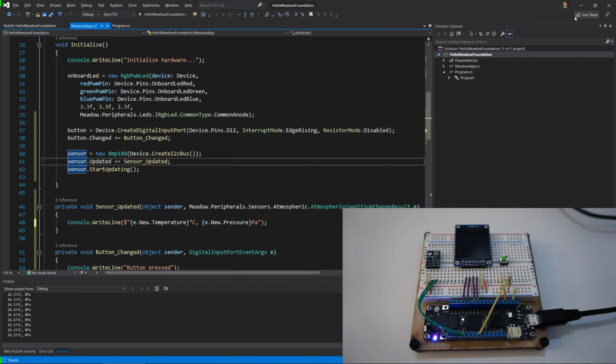And so what that really lets us do is lets Meadow control the speed. So Meadow controls that clock, and it dictates how fast data goes back and forth. And then there's 2 pins, one's output and input. So the old way of saying it is master out, slave in. I'm going to change that to Meadow out, SPI peripheral in.